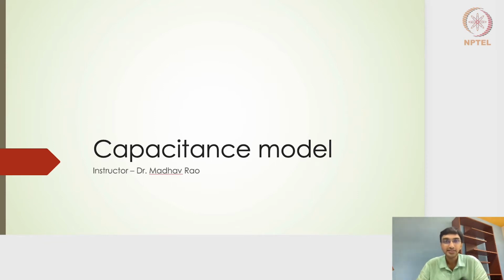Again, the capacitance is of huge importance because the performance of any circuit design, especially in digital systems design, is heavily dependent on the capacitances associated with it. In a particular critical path from the input to the output node, if I want the signal to be propagated, the delay associated with that propagation will depend on the capacitances associated with it. And that is where the capacitance extraction of the transistors designed for the system becomes very essential.